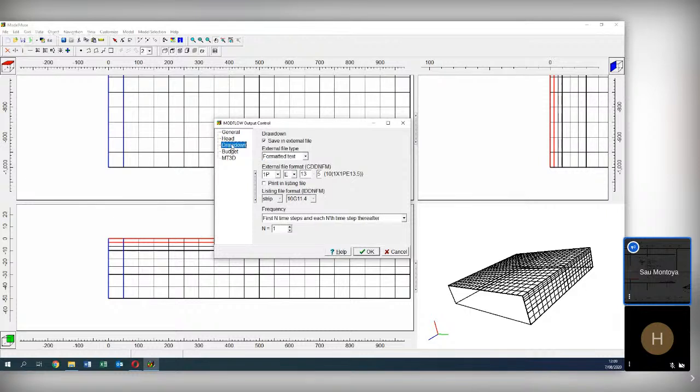The drawdown is also in formatted text. Since this works on Fortran, you can define the unit type, whether you want exponential or decimal, and you define how many time steps you will print out in the files. For example, if you have a complex model that creates such big output files, you will define only certain times to be the files that you want.